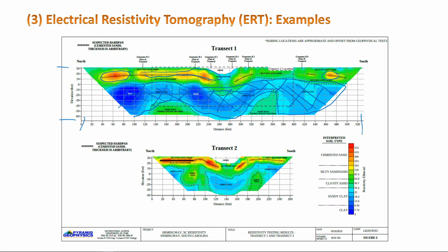So now if you want to conduct a pumping test, before you conduct a pumping test, if you have an image like this, it will show you what would be the best place to conduct your pumping test. Here you have silty sand or sand, and that's not really a very good aquifer because it's mostly clay, sand and silty sand.